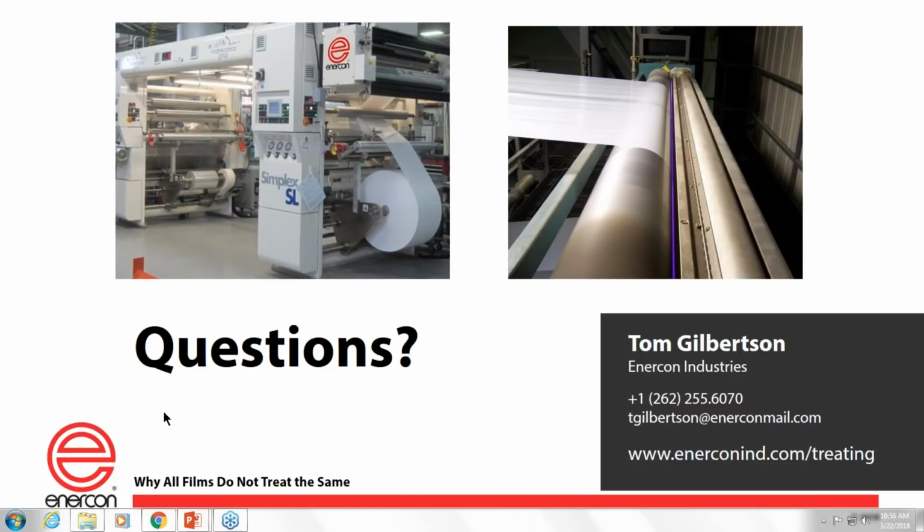So I'll give you an example. Let's just say we're on a printing press again, and we're running standard converting grade film. So meaning we're running polypropylenes, polyesters, polyethylenes, and we're running in typical speeds, 500 feet a minute, water-based printing, nothing out of the ordinary. Could you use a flame treater, an atmospheric plasma treater, or a corona treater? You could use all three. You could use any one of those three, and they all would result in a good ending for you. The downside is you would spend multiples of more money for the flame and the plasma treater without getting any benefit outside of the corona treater in that example.